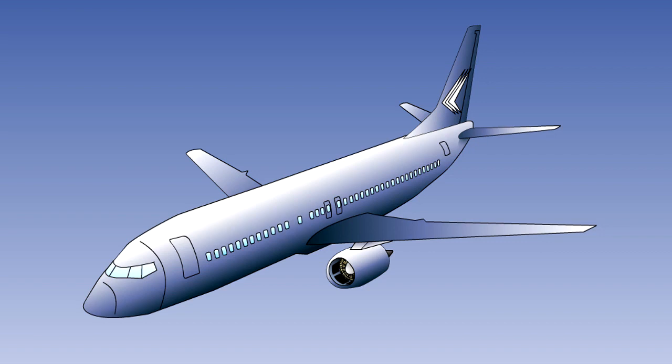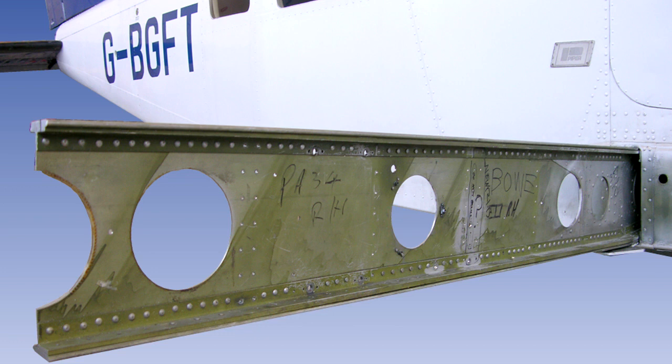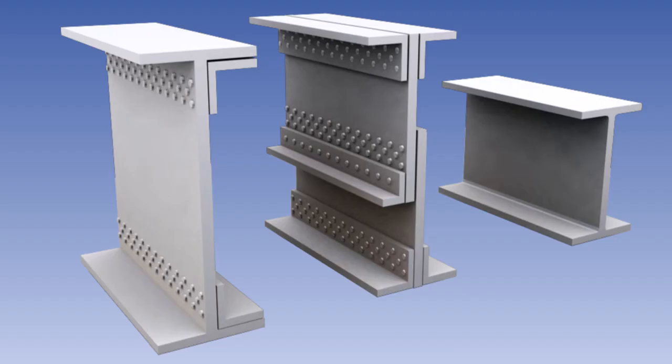Now we will look at cantilever wings, the design used by most modern airliners. The wings have to absorb the stresses due to the lift and drag in flight, and, if of this design, their weight when on the ground. This is achieved by building the wing around one or more main load-bearing members known as spars. The wing spars pass from wingtip to wingtip either as single structures or as connected sections. The spar will normally be an I-beam either manufactured as a single part or made up of 2 or more parts to give it fail-safe characteristics.